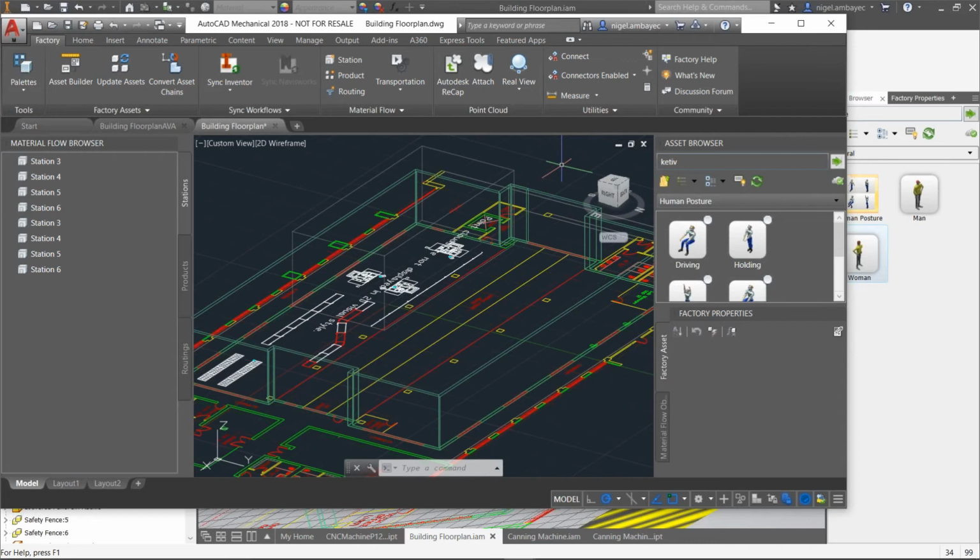There are a lot of questions, so let me go ahead and take care of a few of these. Can you place an asset at a different level than the floor of a layout? So you need something in space that operates above the equipment. Totally. When you put these objects down, you select a point in which they go to, whether that's clicking or actually typing that point into the command line. You can totally do that as well. Same thing in the Inventor side. It's probably easier to see on the Inventor side too. So that works.